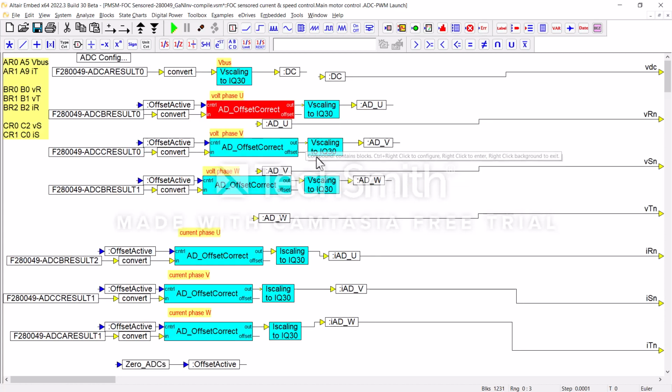What that's doing is a slight filter while it's in zeroing mode. And what happens is when the part first boots up, it sets all the PWMs locked at 50% duty cycle. So phase to phase, there should be no relative voltage difference. Whatever the voltage is on that channel, we call that 0.